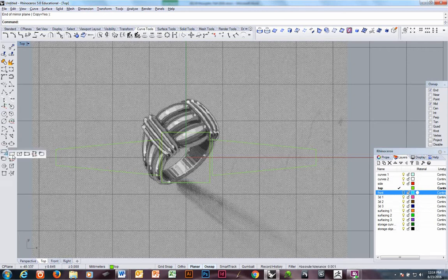All right, so it'd be really marvelous if they would let me orient this box shape however I want, but they won't. So I'm going to outsmart them. Right now, I'm going to put in an ellipse diameter starting in the middle of this, or the end of this middle flute, top and bottom, side to side.